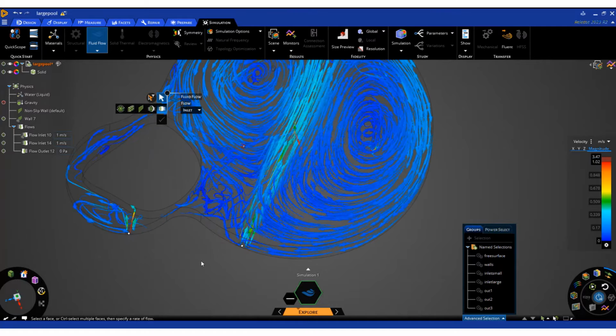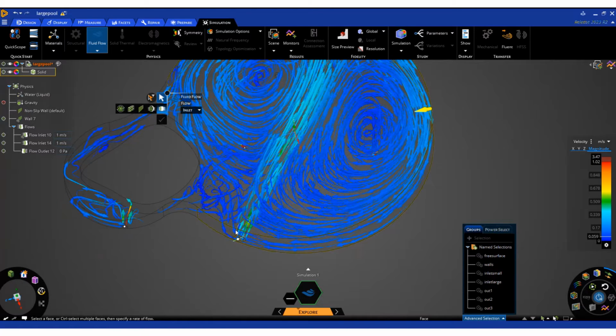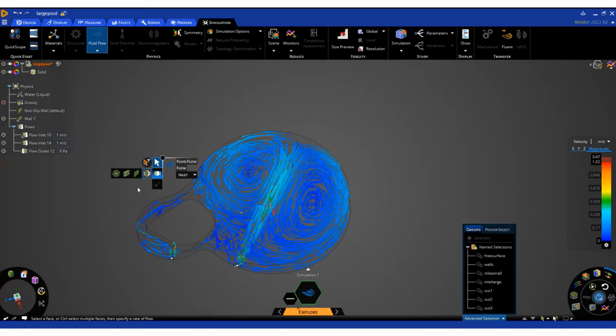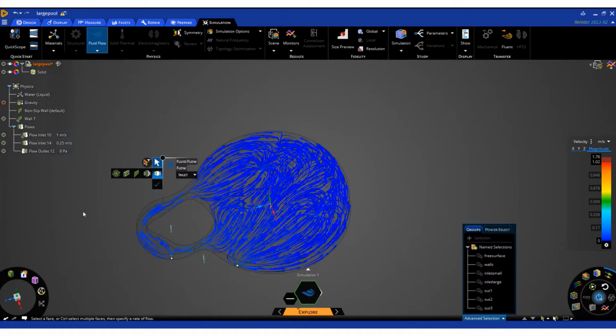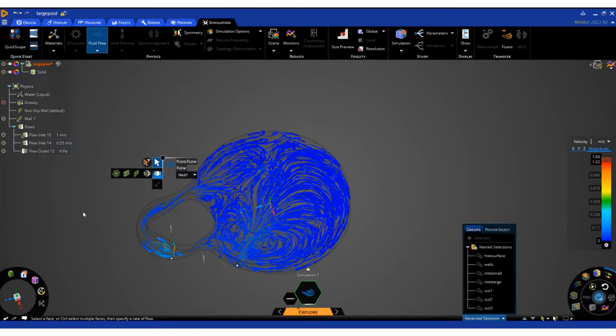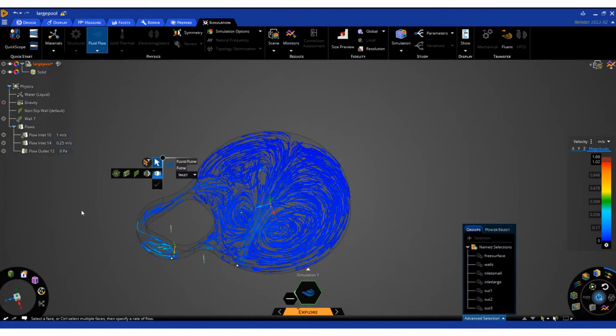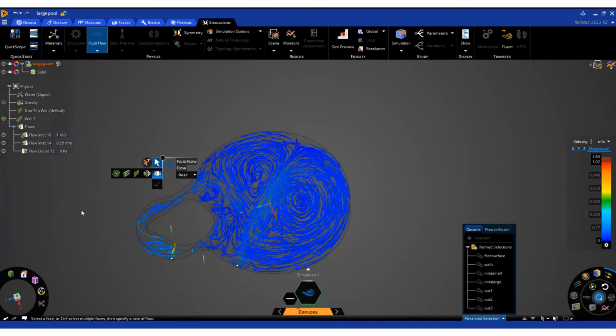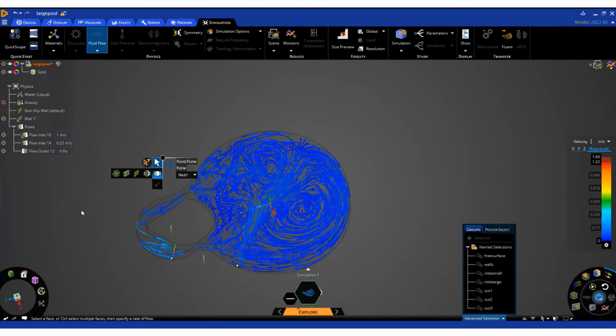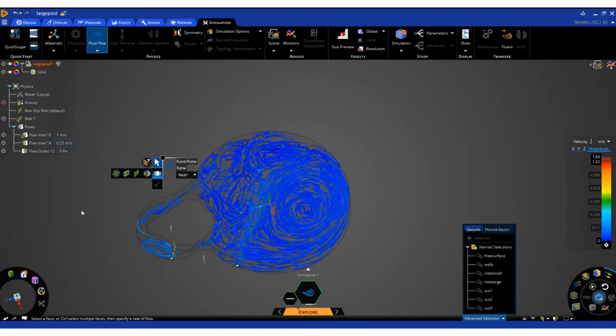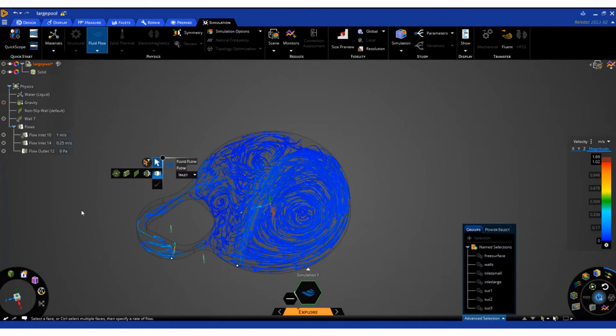And you can see just by adding a secondary inlet, how the flow in the system has been completely changed. And the calculation hardly takes a few seconds. Now what I can do is change this value to a lower value, and the flow will automatically update again. So you can see how multiple design changes can be done in order to understand the flow behavior inside, say, for example, a commercial pool.